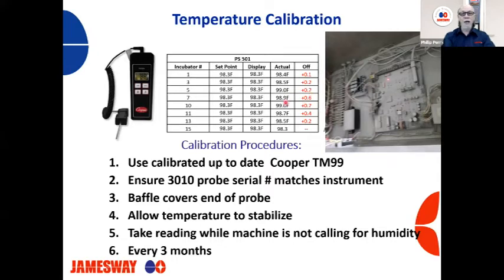I was at one hatchery where, usually when you get the electrotherm certified and calibrated and sent back, it'll have an offset value. I don't like to have my calibrator more than 0.1. And when you purchase one, you can ask for the probe to be within 0.1 at 100 degrees. And what had happened with this hatchery, it had an offset value on the probe of add 0.5 to the reading.